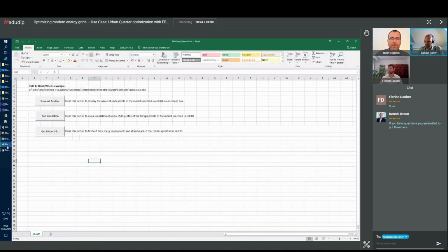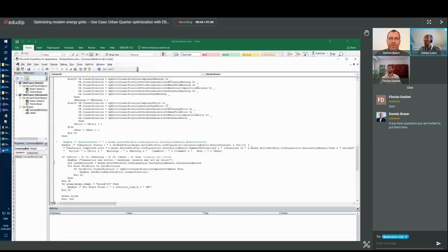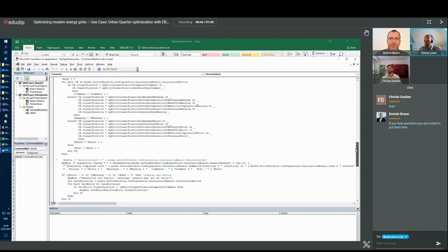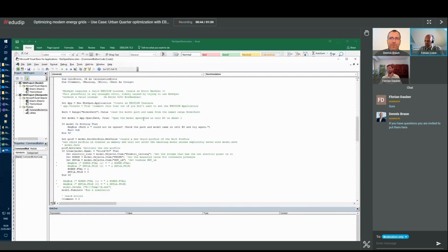And finally, I would like to show our interface which drives all this, because it's more or less Excel VBA, or you can also use it in C#.NET or from C++. Here we have a little bit of VBA code, which uses this application's open interface. This is a driving interface, and we always start up with the application, and we open models, and we get back a model, and then we can access the objects of the model and run simulation.